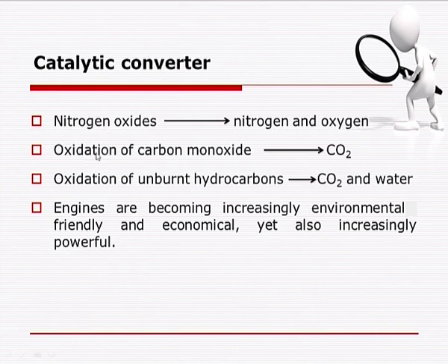So, in the catalytic converter, oxidation of carbon monoxide takes place and we get carbon dioxide. And the unburnt hydrocarbons present in petrol and diesel, the catalytic converter oxidizes them and changes them into carbon dioxide and water, which is not dangerous for the environment. Engines are becoming increasingly environmentally friendly and economical, yet also increasingly powerful. The engines will be more powerful now.